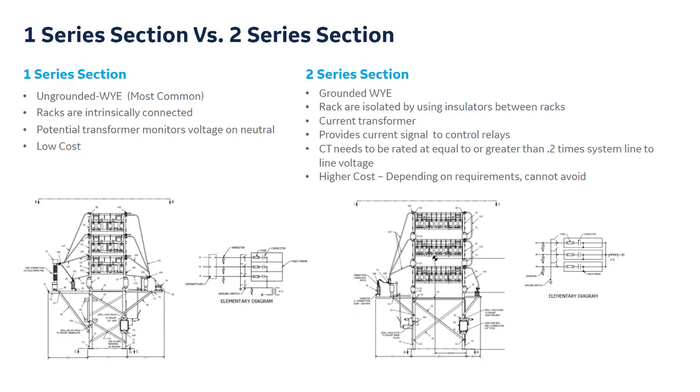The simplest method to detect unbalance in single ungrounded Y banks is to measure that bank neutral or zero sequence voltage. When the capacitor bank is balanced and the system balance equals 0, the neutral voltage will ideally be 0 as well. And a change in a phase of the bank will result in a change in the neutral or zero sequence voltage, which will then, like I was saying before, drive a relay for an alarm or a breaker close.